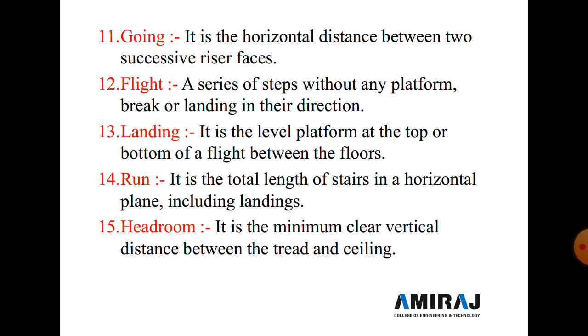Now next is flight. A series of steps without any platform, break or landing in one direction is known as a flight. Now next is a landing. Landing is the level platform at the top or bottom of the flight between the floors, known as a landing. Now next is a run. It is the total length of the stair in a horizontal plane including the landing, known as a run. Headroom is the minimum clear vertical distance between the tread and ceiling.